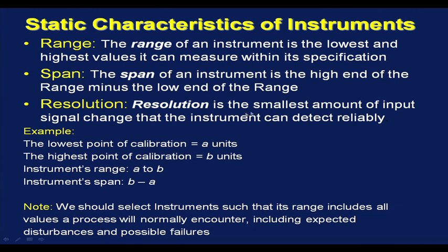Resolution is defined as the smallest amount of input signal change that the instrument can detect reliably. It should be noted that we should select instruments such that its range includes all values a process will normally encounter, and that we should include expected disturbances as well as possible failures.